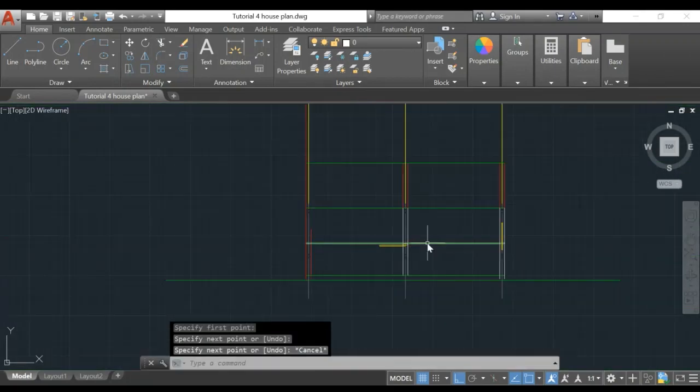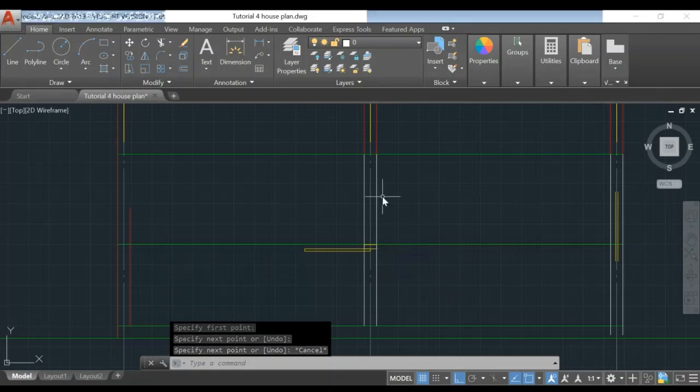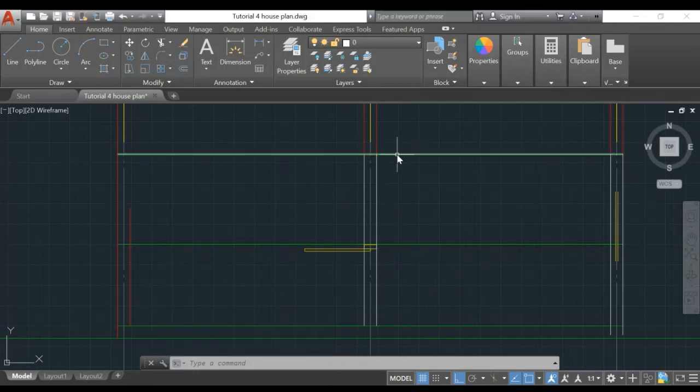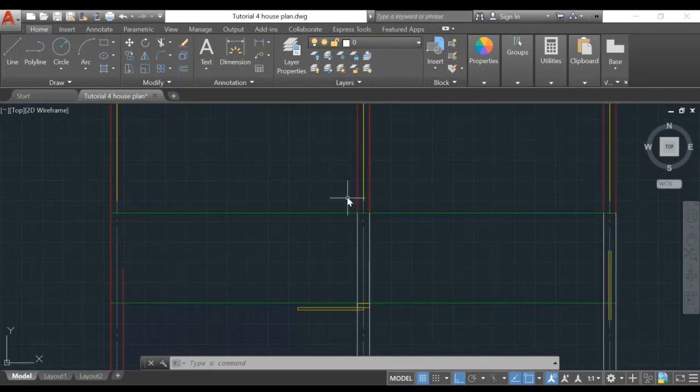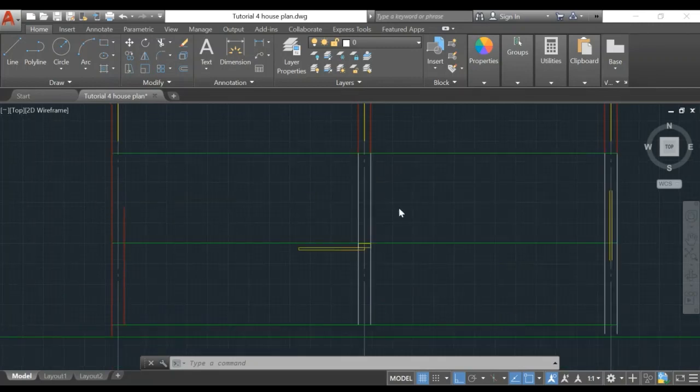So why is the color of the wall here white? Because when you cut the door here, at the back of the door, the wall will be at the back. So it should be white color, 0.2 pen, because we did not cut the wall, we cut the door. Meanwhile, on top here, we cut the walls, so it should be red color with 0.4 to 0.45 pen.